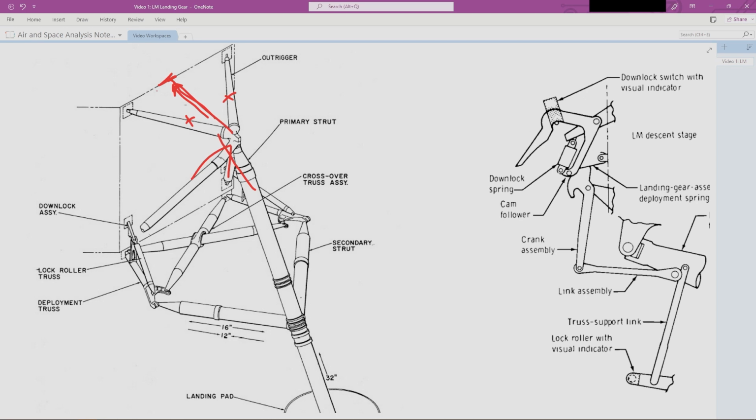And if the lunar module structure is set up in such a way that this corner is very stiff and this corner is very stiff, when it's interfacing with other panels and members of the spacecraft structure, it might have been more efficient to just send 2 struts out to these corners than straight to the middle.